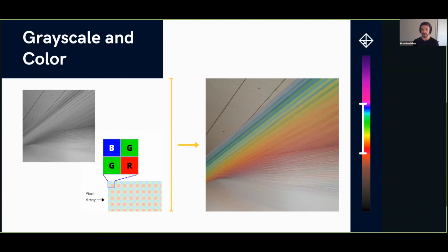You can add other dyes there. There are plenty of other ways to do this. I expound upon some in my blog post because you don't always want to mimic the human eye, right? If red is important to you on the road, say, you would just add a red filter and be done with it. That's all you needed. But for photorealistic images that mimic what we would see, BGGR is most commonly used. It's an industry standard, and most importantly, it's produced en masse. So you'll see it everywhere.